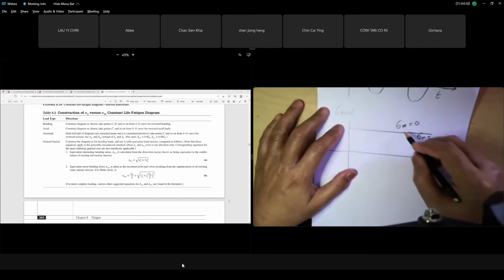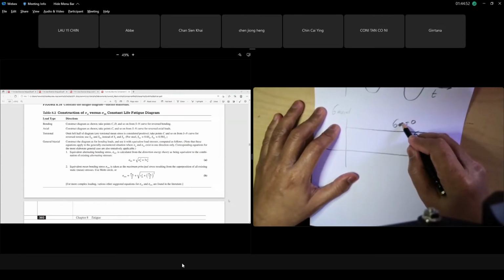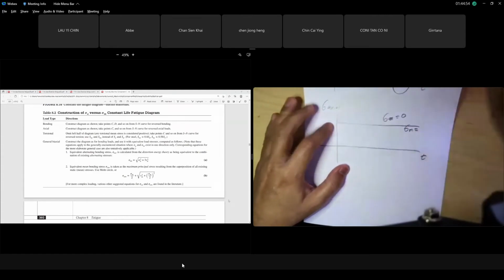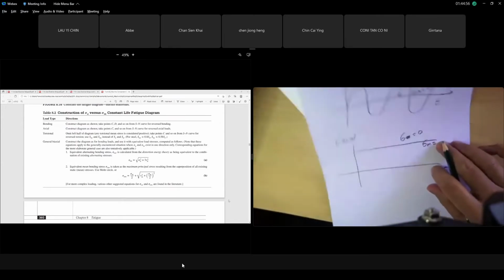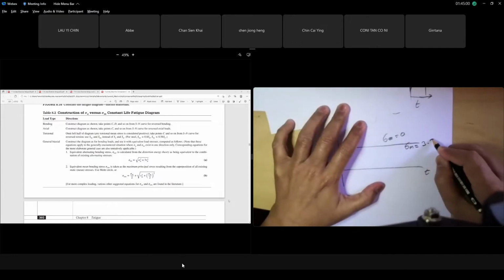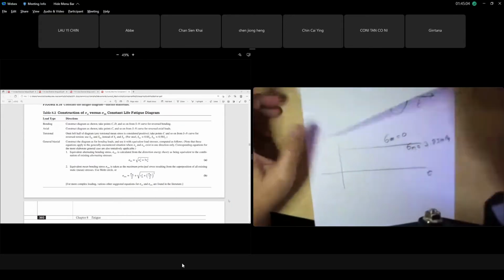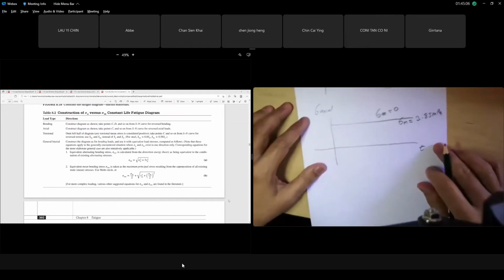So it means axial stress is mean. We only have mean. We don't have amplitude. We don't have alternate. We only have mean. The mean we calculated just now is 3.85. So the sigma mean is 3.85 megapascal. We multiply by KF axial. So we have only this one.